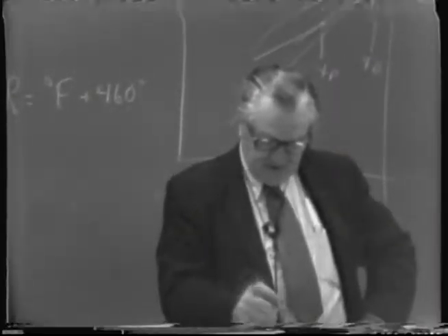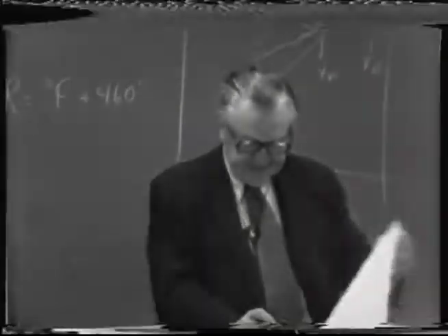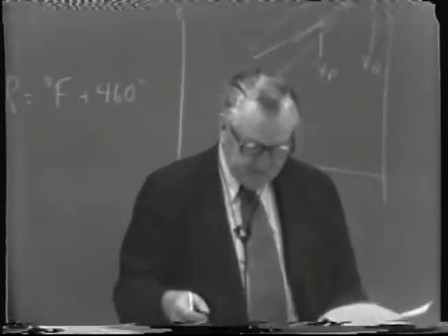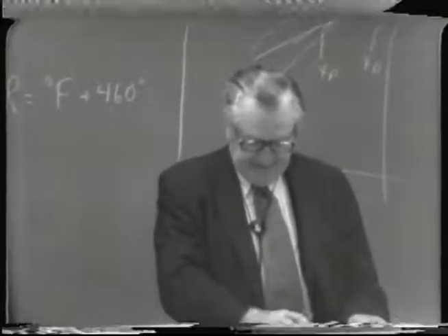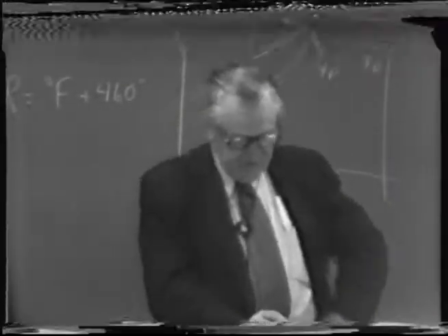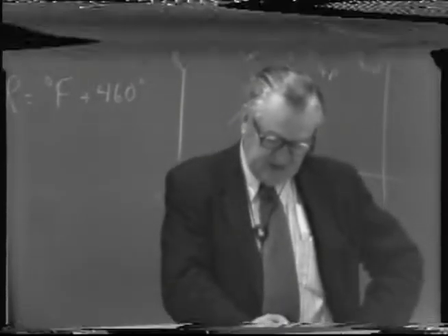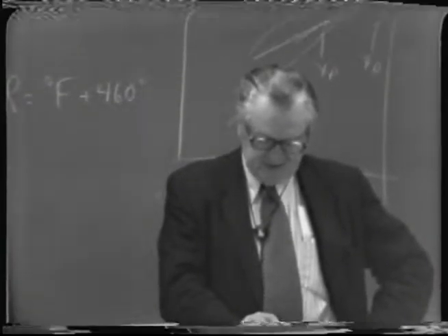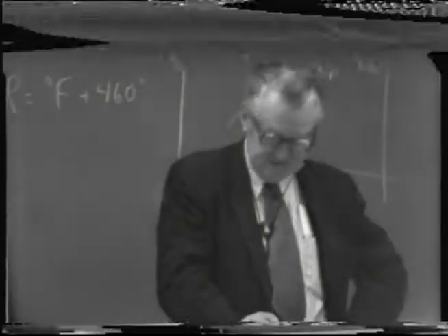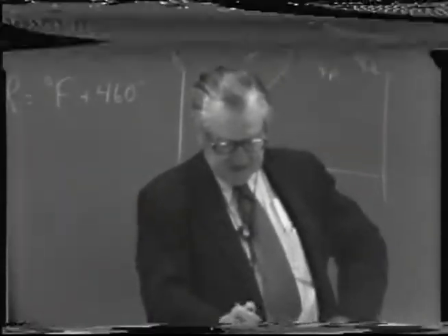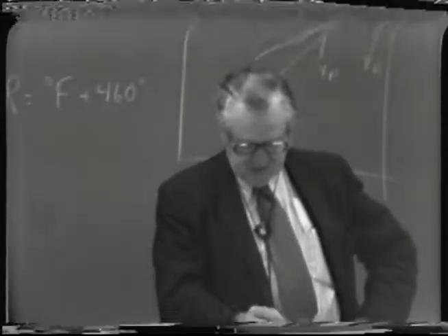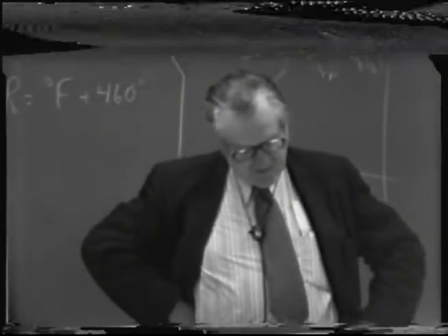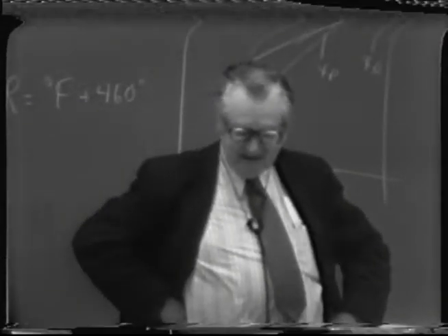Well, anyway, if we say then that this is the, using the symbol capital V for the volumetric vapor rate, this is equal to the linear velocity, small v, times the cross-sectional area in square feet. You see, if you multiply square feet by feet per second, you get cubic feet per second, which is what the vapor rate is expressed in. And of course, the cross-sectional area in its simplest form is pi d squared over 4, so you're substituting the values in, solve for d, comes out to be about 8.8 feet diameter of the rectifying section.